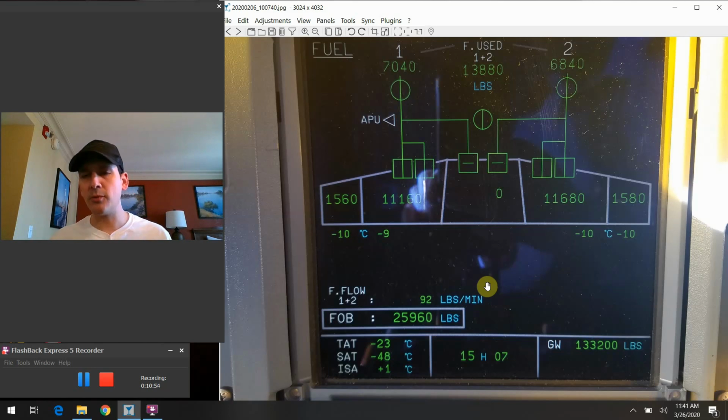We're also checking out, and that's one thing I should say from a high level standpoint, we're monitoring our fuel burn every time we go anywhere to guard and look out for the case of a fuel leak. You would notice this by comparing the quantity that remains in the tank to where you are, once again, at your specific point in time over what point of navigation or whatever that's been laid out ahead of you as part of the normal flight plan. We're always looking and watching out for these things.